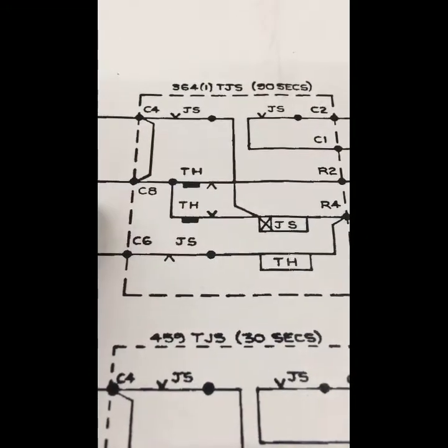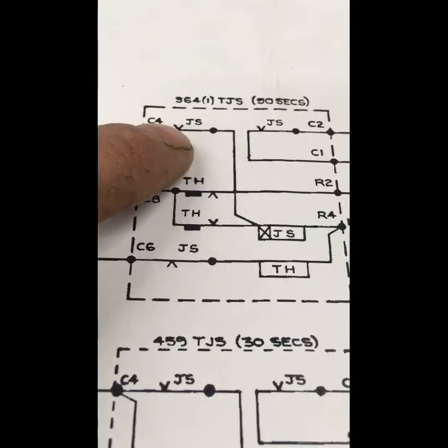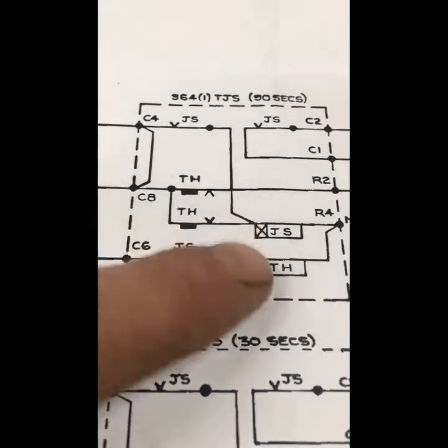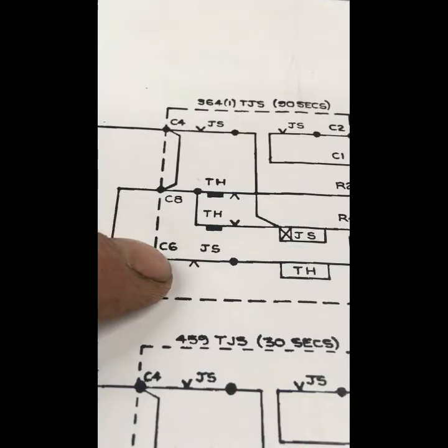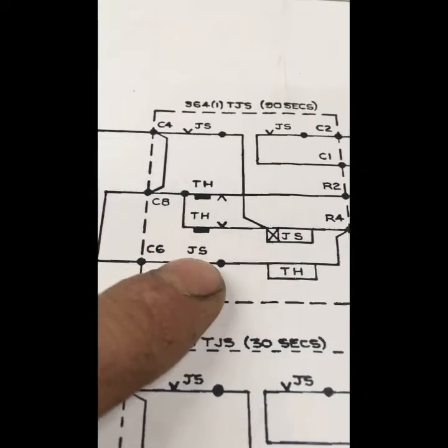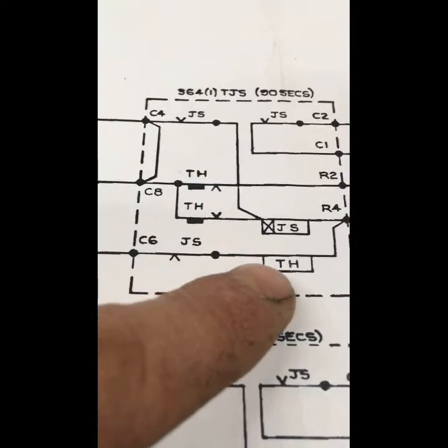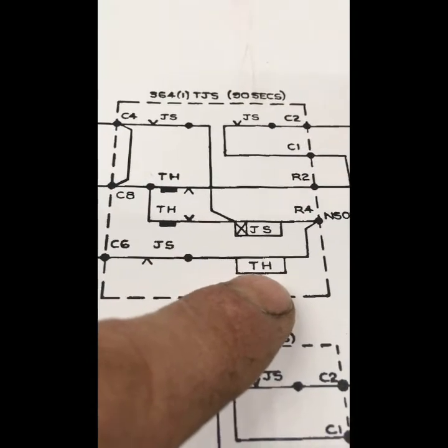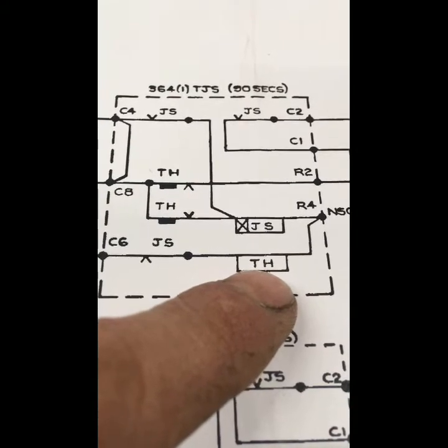Now, we are going to go down and drop on the bottom one, because as we've already mentioned, our JS is not up, it is down, because our relay is not being powered. So our path is provided for our 50 volts to flow along through the contact of the relay, timer relay being down. Starts the thermal element timer by heating the coil, so the bimetallic strip now starts to bend.